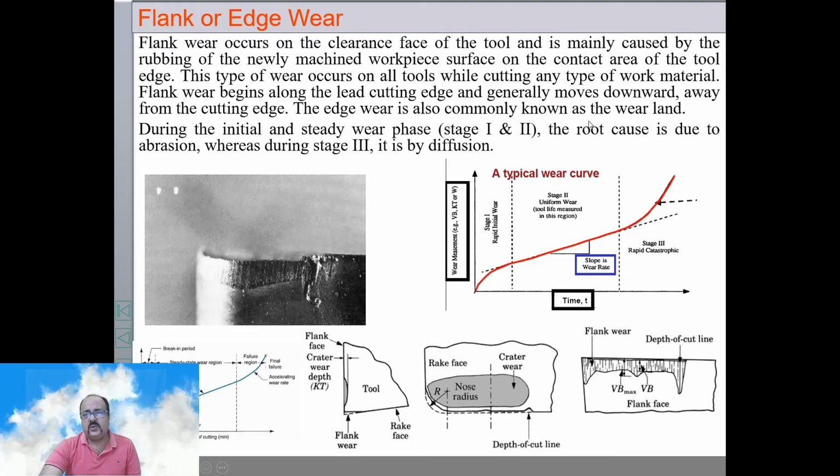Edge wear is also common, known as wear land. So this is flank wear or edge wear. We will call it flank wear. Now it has been plotted. If you plot the tool life and the wear, this distance here, how much it is wearing with time,